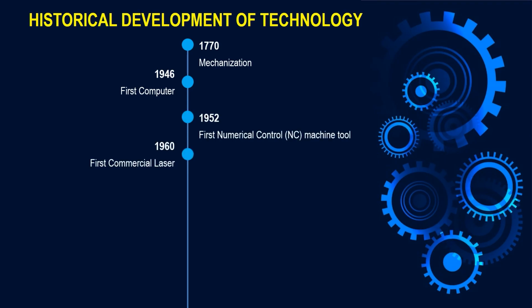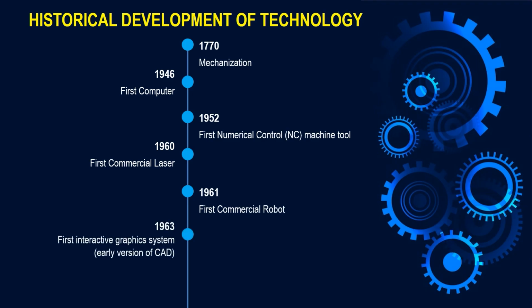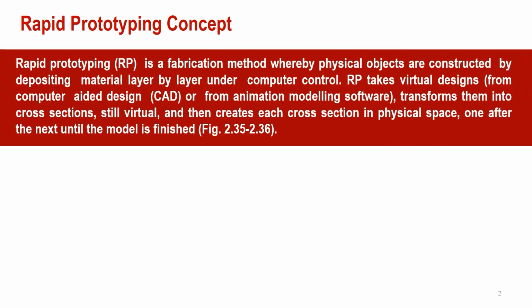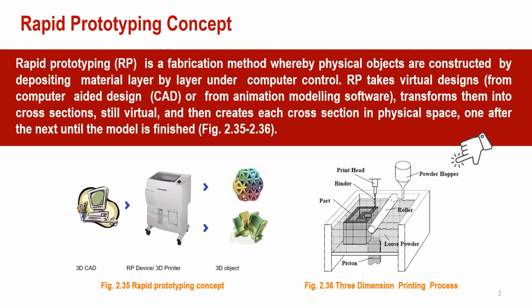This started with the use of an HP based printer, specifically the inkjet printer. The idea was to use a cartridge; where the inkjet uses one nozzle, they use two nozzles. From one nozzle you can see over here the powder was being sprinkled, and from the second nozzle the binder was being sprinkled. So layer of powder, layer of binder, layer of powder, layer of binder, it leads to the 3D printed parts.